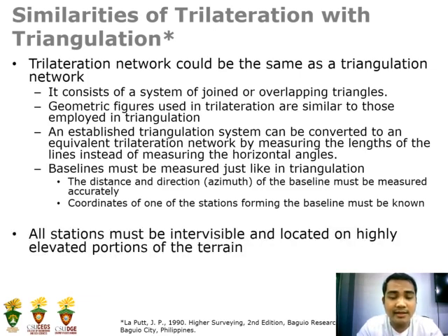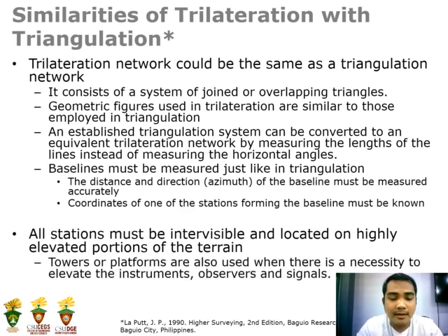And the second similarity is that all stations must be intervisible, and located on highly elevated portions of the terrain so that they can be seen more easily. And towers or platforms are also used when there is a necessity to elevate the instruments, observers, and signals.